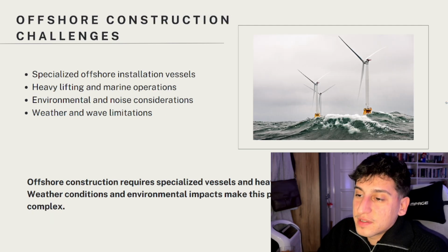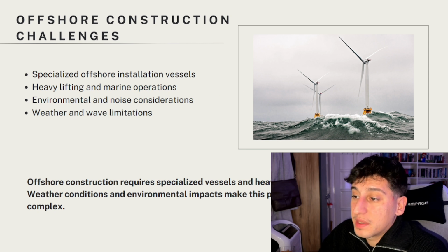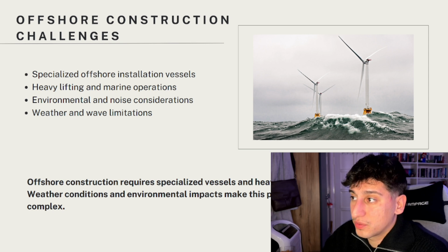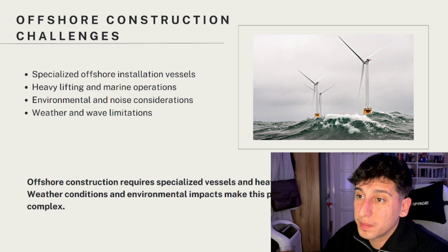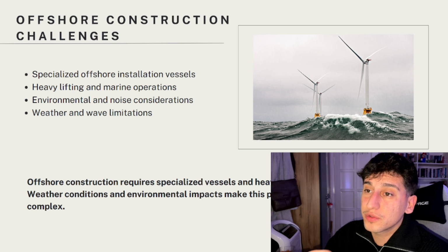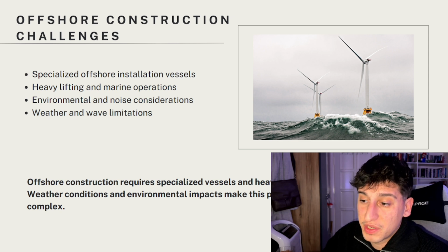Of course there are some offshore construction challenges too, and they are really unique, because there are heavy installation equipment and specialized vessels, and you need precise timing to build them safely. Also, when you're building monopiles, you are disturbing marine life because you are making a lot of noise. So, to be able to block that noise, engineers should calculate some noise mitigation measures.